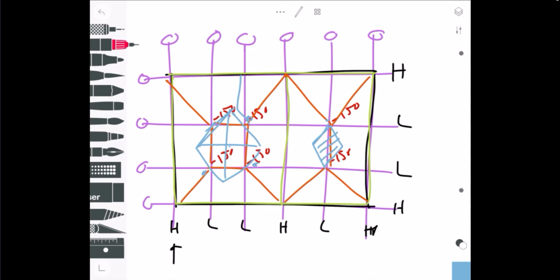And actually, it wouldn't look that way. It would look more like this. It would look something like that, and you have a drain there, there, there, and there. It gets a little weird, but anyways, that's the whole idea. You have a high point, and the insulation would slope down to these points, and you just have a large area of sloped insulation there.